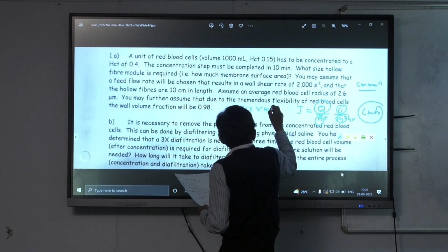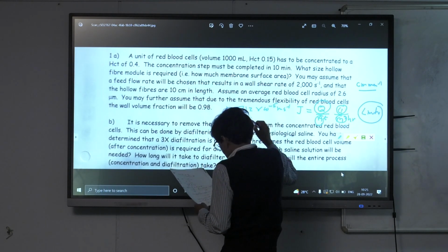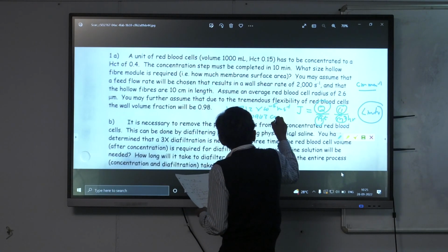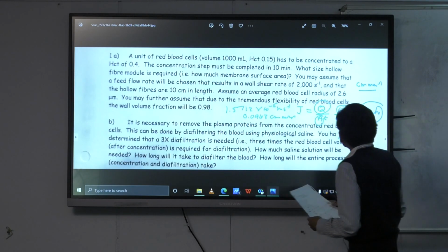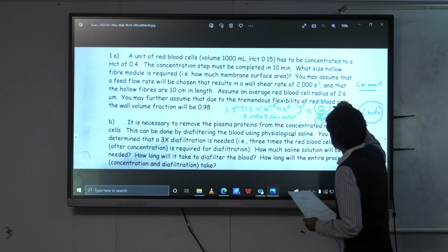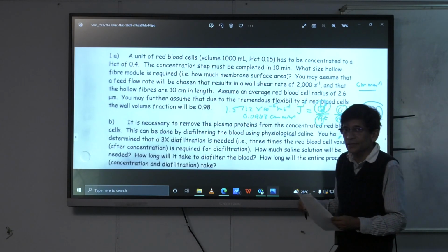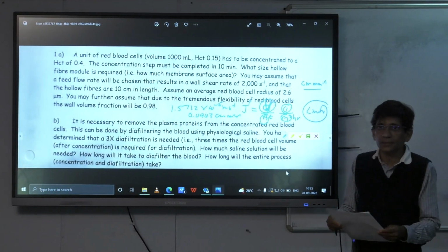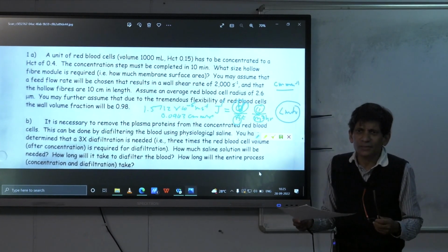So anyway, I get, and we'll put this solution up, 1.5712 multiplied by 10 to the minus 5 meters per second, which in centimeters per minute is 0.0943 centimeters per minute, okay? So once you know that, then you know J, right? You know the volume you have to remove, you know V, you know T, you can get area out of that. And the area I get is 663 square centimeters. So it's a little different, but I suspect your error was a unit conversion error somewhere.